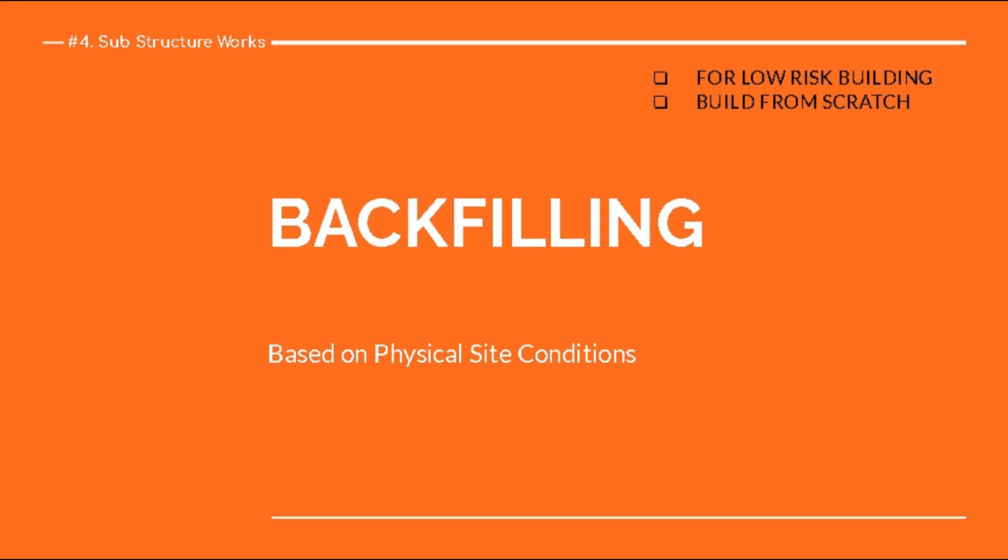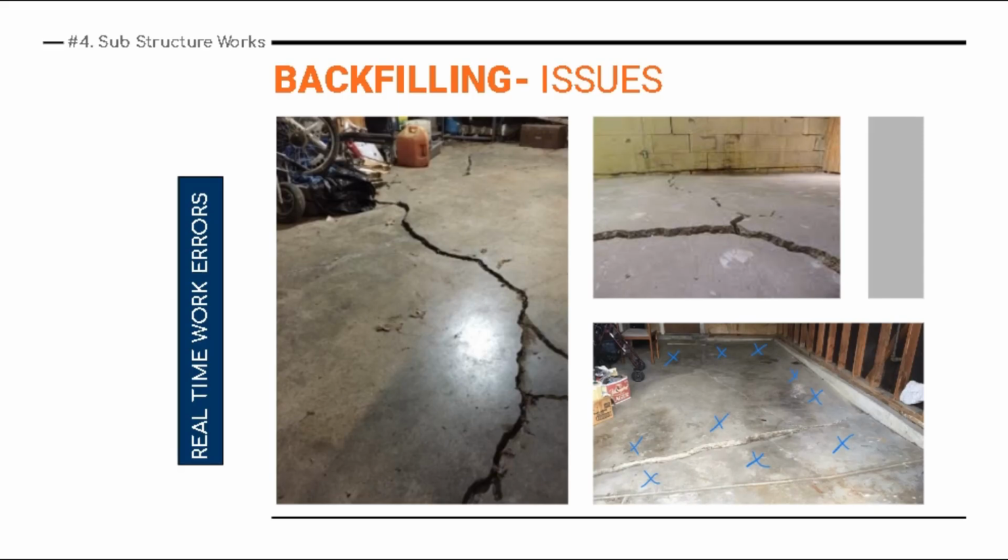Remember, backfilling has a very important role to play in this entire building construction process, because once you neglect this, you can understand the consequences as in here. You can see these big cracks in the floor. These are real-time work errors, the various issues that have happened due to negligence in backfilling works. If you don't compact the soil properly, this is going to happen.